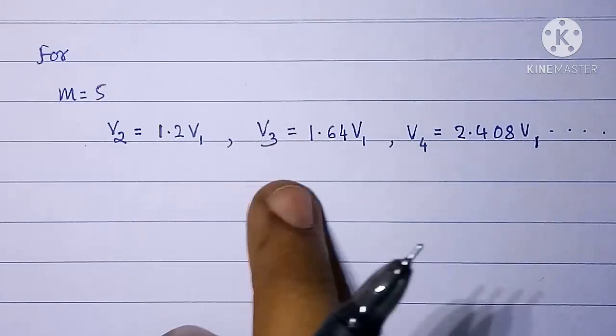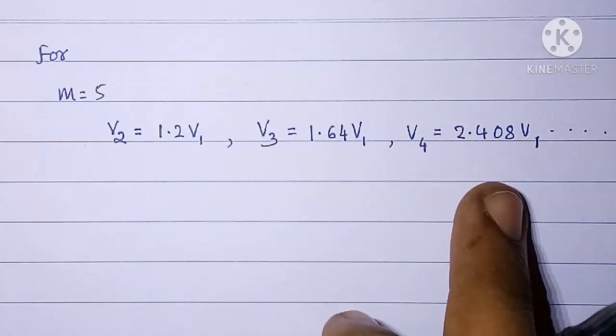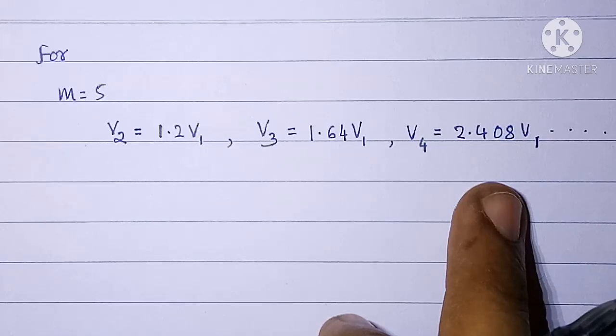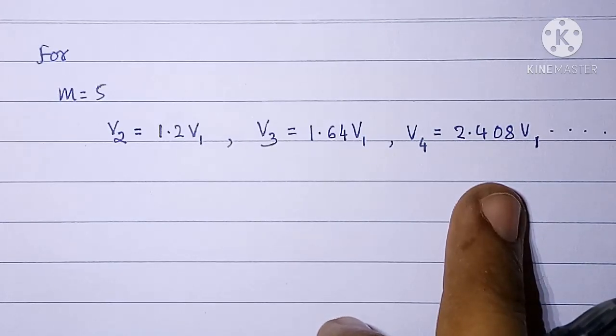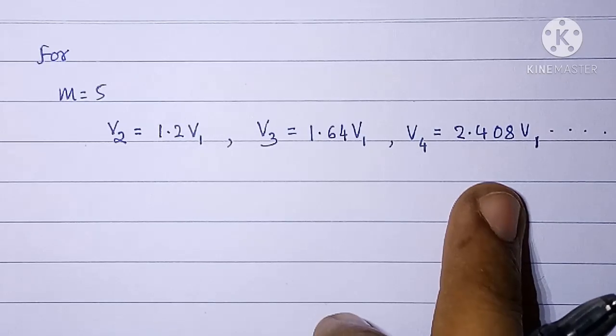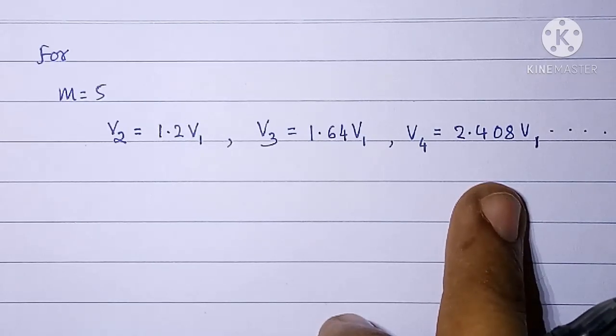So based on how the voltage is distributed across the various units in a string, we define a new term called string efficiency.